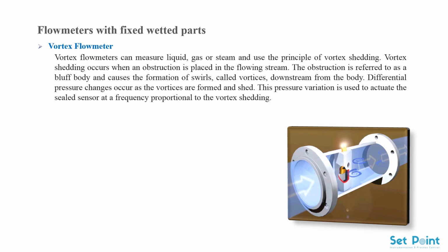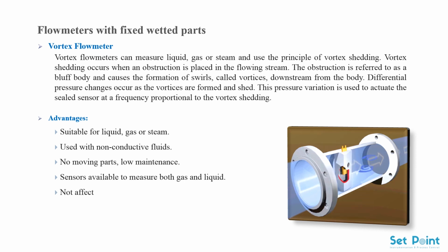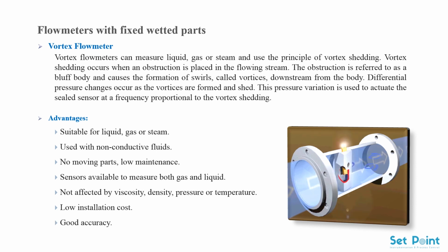Advantages. Suitable for liquid, gas or steam. Used with non-conductive fluids. No moving parts, low maintenance. Sensors available to measure both gas and liquid. Not affected by viscosity, density, pressure or temperature. Low installation cost. Good accuracy. Linear response.